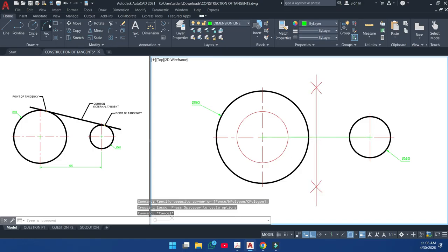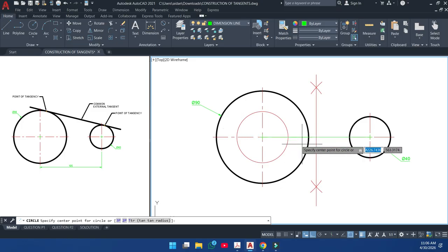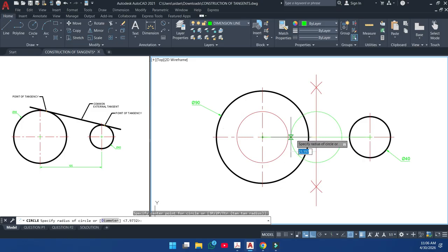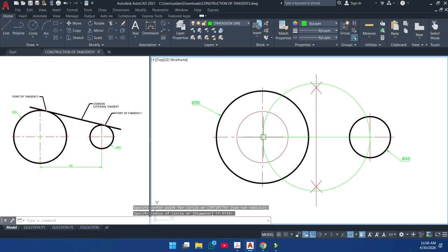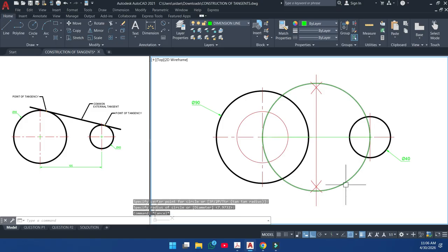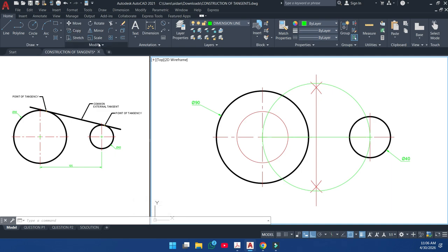Now, using your radius command again, lock it in the center where the triangle lights up, or the intersection point here, open outward. And this point here, center of the circle, and drop a line. Now, you don't need this whole circle, so you could trim off the below half of the circle. You could use the break command, click on break, come anywhere here, so click on it on this side here and click, so you will actually break this piece of the circle out.